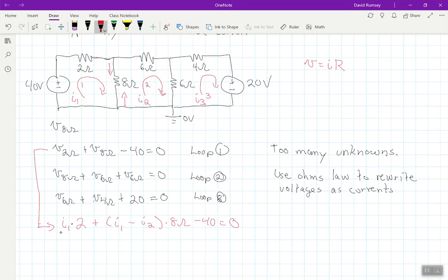So now I have a new loop equation. Before I simplify this, I want to emphasize that if I had drawn the loop counterclockwise like this, then I2 would also be going down, and I would have I1 plus I2 because they're both going down. But I drew it clockwise, and one is going down and the other is coming up. So that's why it's a negative or a subtraction there.